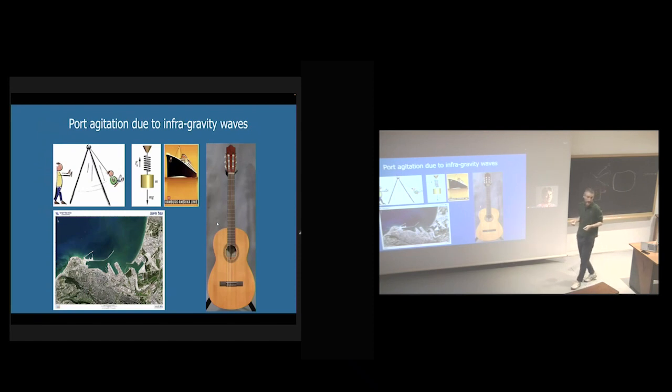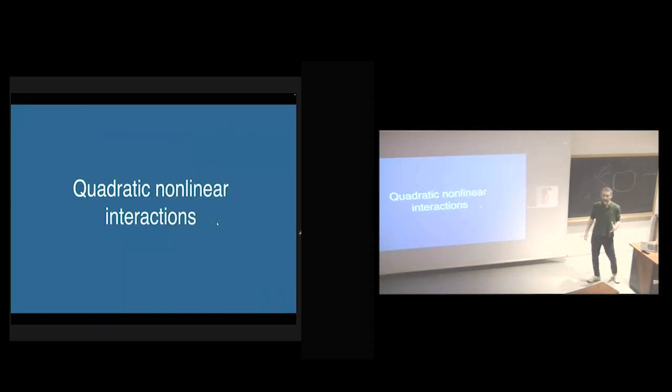These ships have natural harmonics. They're also moored to the base. So if you are hitting their natural harmonics with these waves, you have a mess in loading them, and you can break, I don't know, the decks of the ships, and they can resonate with their moorings that are also springs and sway to the port. So that's kind of important for harbor design. Even if you have the harbor, you need to design the stiffness of your mooring system, yeah? Just not to make it resonate.